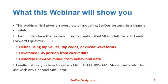What this webinar will show you. This webinar first gives an overview of modeling SerDes systems in a channel simulator. Then I introduce the process I use to create IBIS-AMI models for a transmit feed-forward equalizer. Define the FFE taps using tap values or tap codes or circuit waveforms. Include the ability to de-embed the IBIS portion from the circuit data to derive the AMI portion and generate an independent standalone IBIS-AMI model from the data. Finally, I show you how to get a copy of my free transmit feed-forward equalizer model generator for use in any channel simulator.